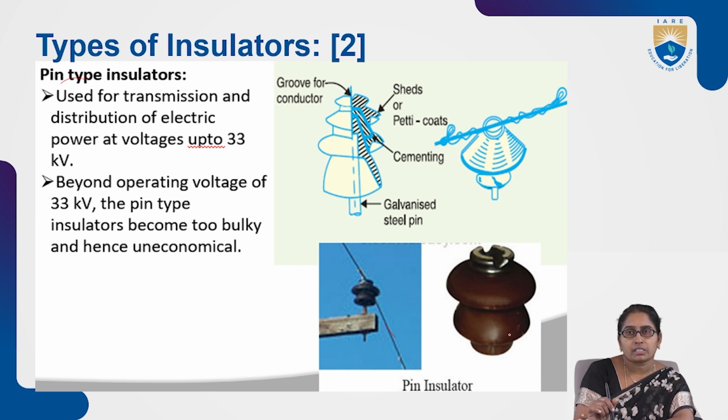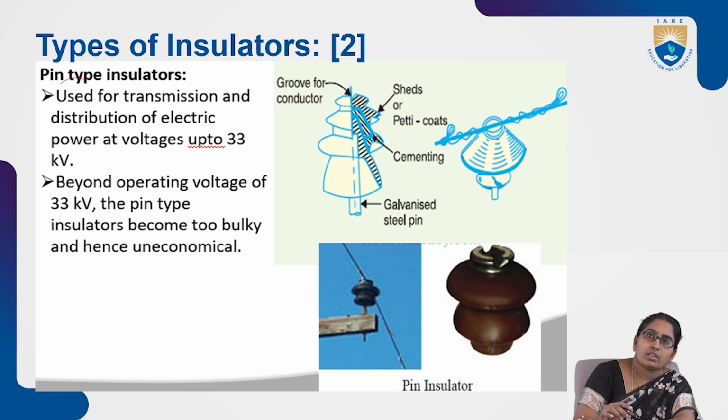You can see beside it a pin type insulator is shown. Look at the diagram: there is a groove on top for the conductor to be placed, and there is a galvanized steel pin. The conductor is placed in this groove.